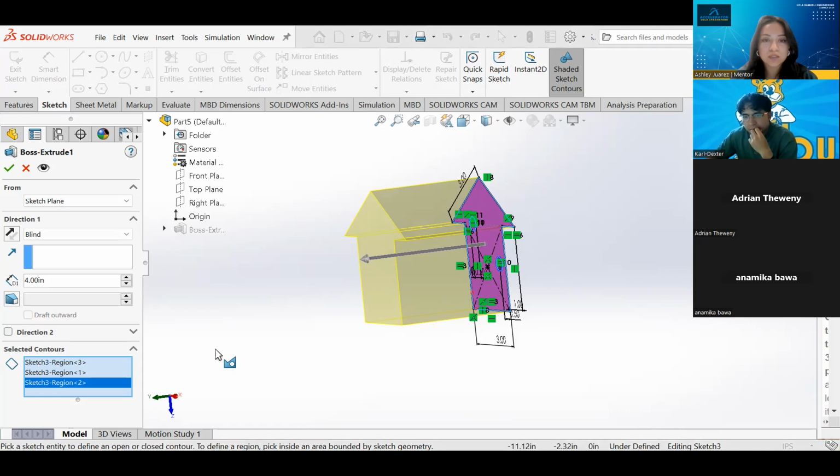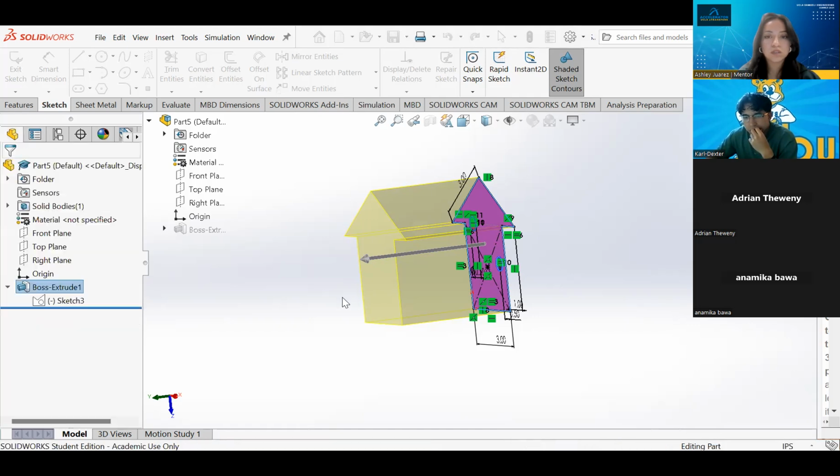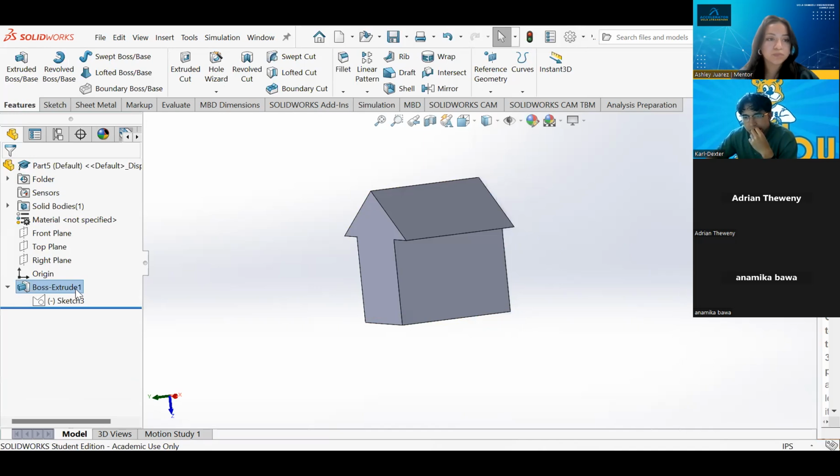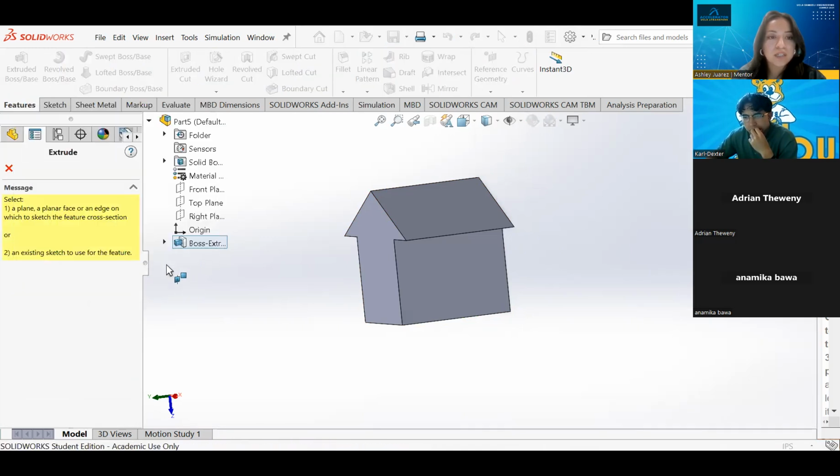Circle is defined. Okay, yeah, that was my bad. Good catch. So let me first show you guys how to enter the extrude one more time. So I want these selected. Cool. To enter your extrude boss, say you want to extrude something, you're gonna click at the top interface here, right next to the sketch tab. You'll see a features tab. Select boss extrude, and then here it should show a sketch.